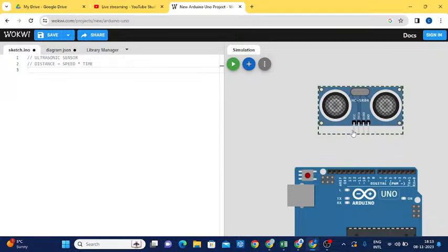You no need to consider those pins, they work commonly. We have to consider the trigger and echo pins, because the values transmitted and received by these two pins are how the data will be transferred. The trigger and echo pins are the data transferring pins.